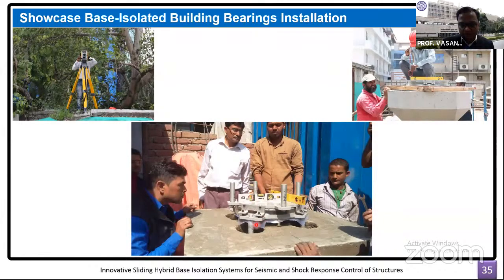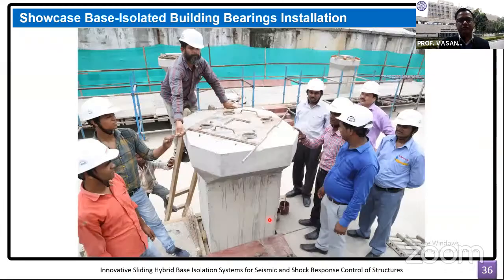In this picture, what you see is how it is connected to the column here from the beneath, and how it will be connected to the column above here after the superstructure construction would begin. And currently you can see that it has been locked. Of course, when the structure is complete and built completely, then this locking will be removed, and isolation will be effective afterwards.